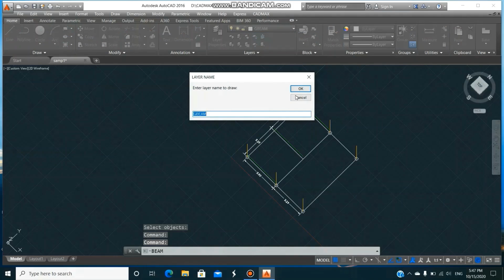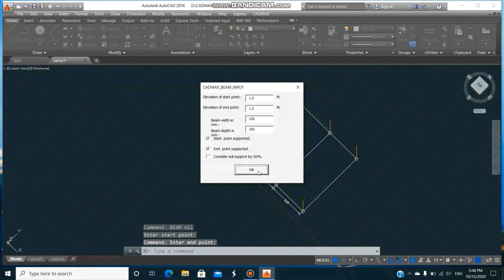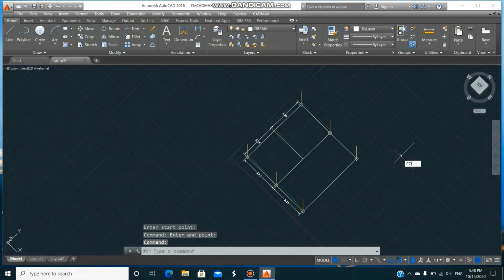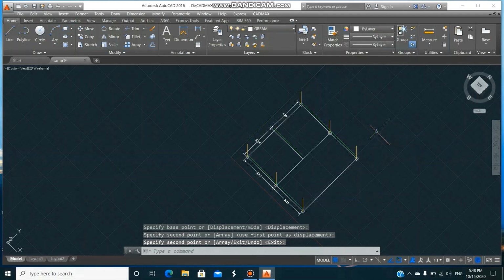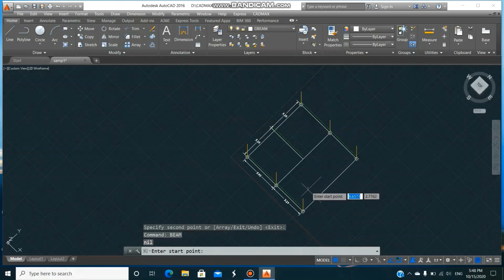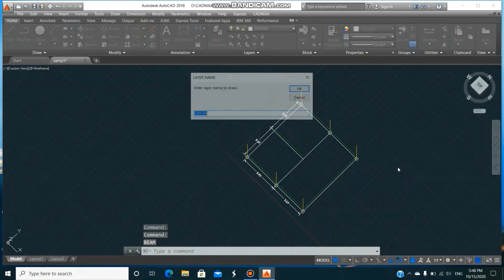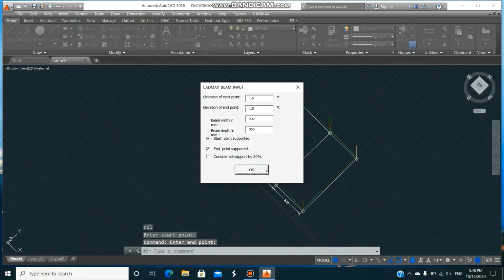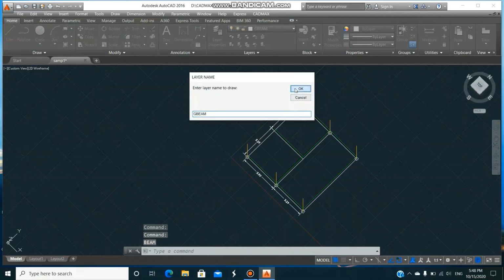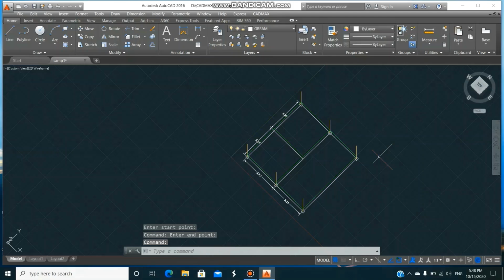Give one more beam. This point to same 230 by 350, and copy the same, this point to this point. Then beam command, can click on the menu, give the same size. Press enter for previous command. So this is the grade beams drawn.